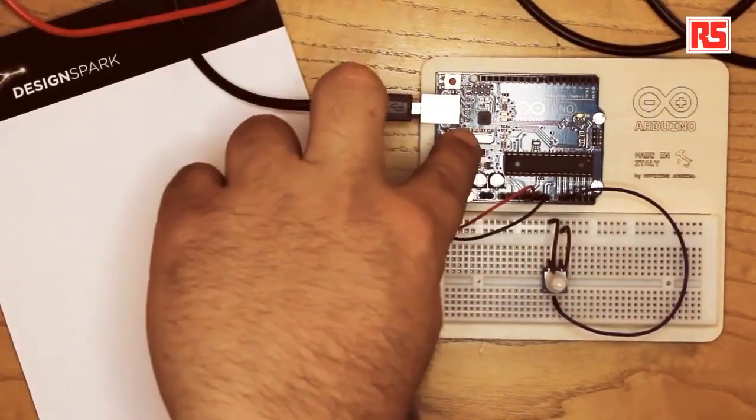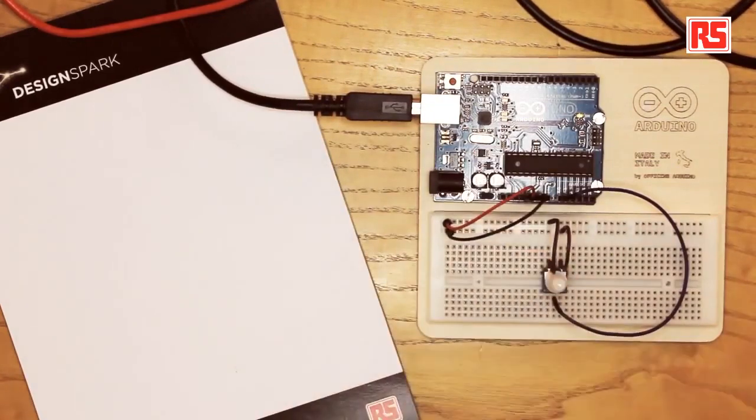So for this project, we're going to be using something called serial communication, because the Arduino will send data over to the computer 1 bit at a time at a certain speed that we will define in software. Then the square chip that you see here will convert that into USB data that travels over to the computer. We have used serial communication in the past in order to visualize the data that comes from the Arduino board within the Arduino IDE.